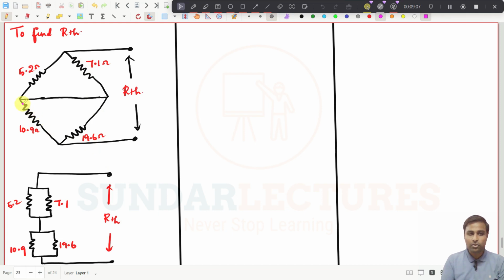Again, these two resistors have both ends connected, so they are also in parallel, and between these two parallel connections there is a connection. That is what I have drawn here; I have just redrawn this circuit. These two are in parallel, these two are in parallel, and these two parallel combinations are connected in series. So it is very simple to simplify this resistor bunch.